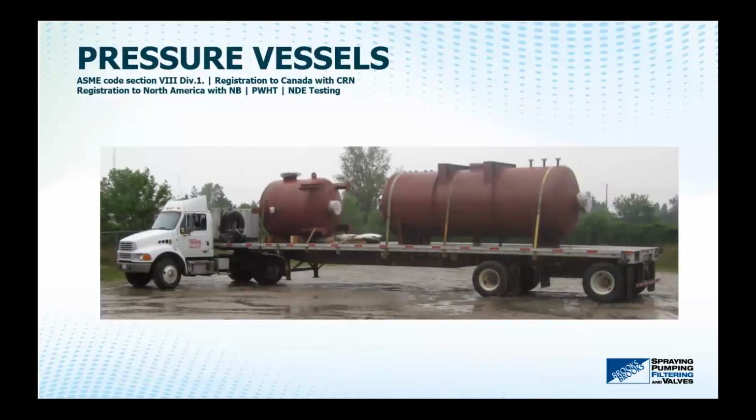And typically the following stage downstream of a separator is we would install a receiver. Again, the benefits of a receiver, it could be considered a bit of a knockout drum, or it's also used to assure that the compressor isn't loading and unloading too much.